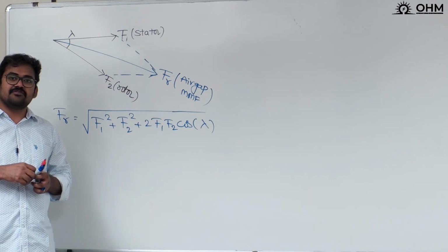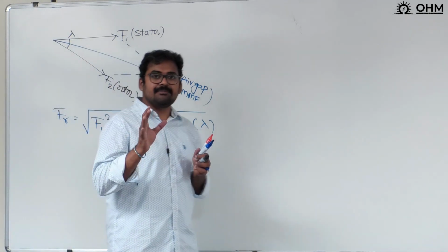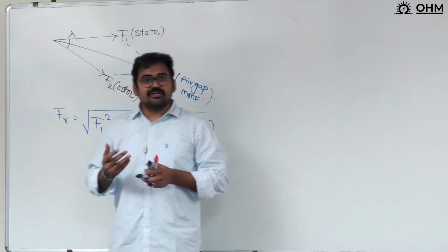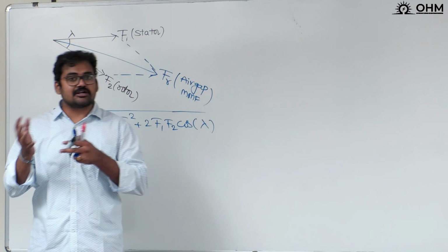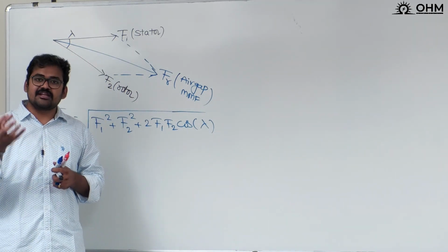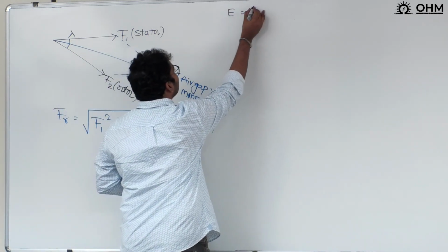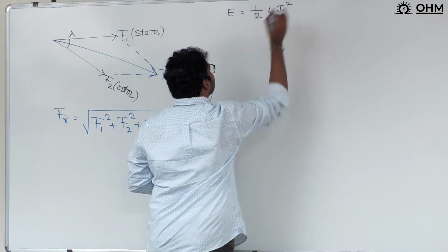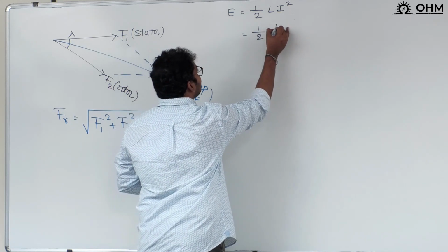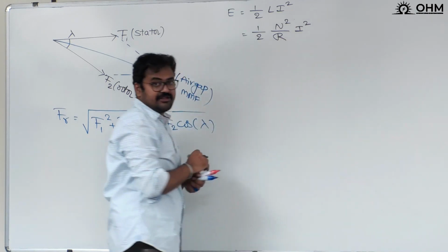To understand the equation for torque, let me first understand what the medium between stator and rotor is. Air medium. In that air medium we have an electromagnetic field. Can you tell me the formula for energy stored by an electromagnetic field? We know the energy stored by a magnetic field is equal to half Li square. And we also know the formula for inductance L. Can I write L is equal to N square by R? Yes, we studied it many times.